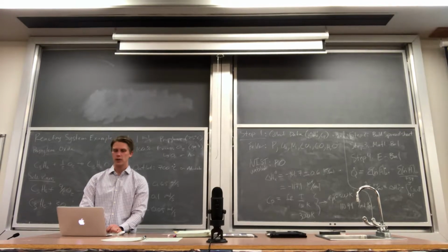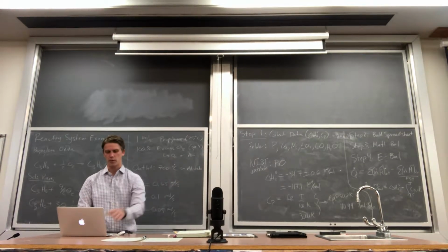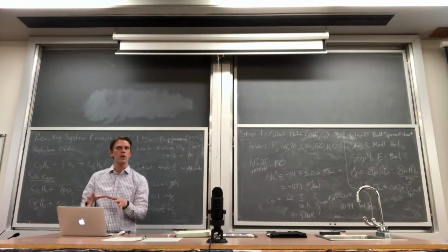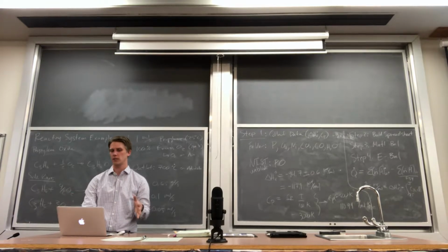This mole fraction equation, that's the same one, right? Mole fraction of propylene divided by the total number of moles. Double checked all of that. And these are all exactly the same equation. Enthalpy, all exactly the same equation, all the same equation, all the same equation. So I really only have to check 3 or 4 equations to troubleshoot this entire spreadsheet.